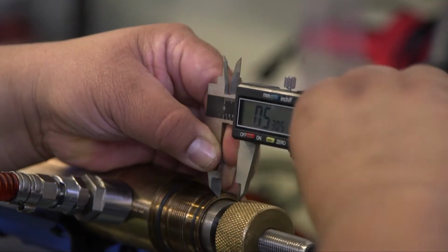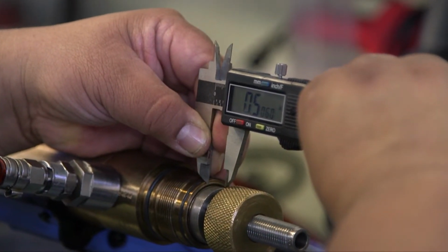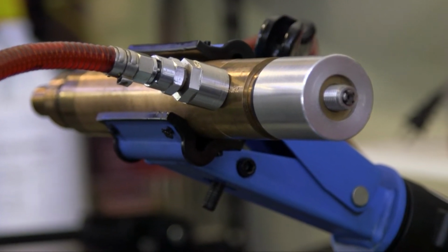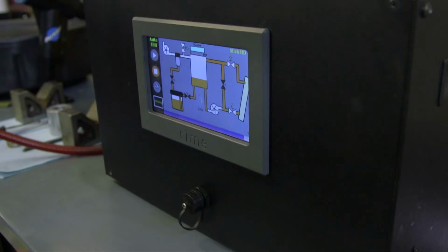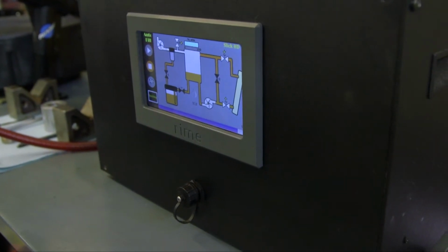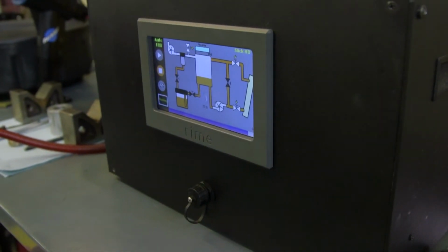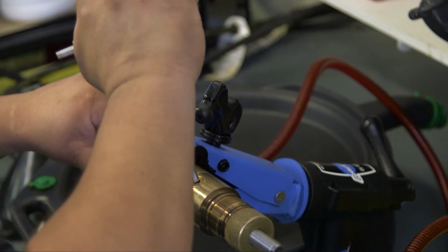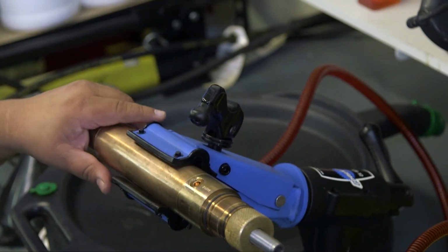The assembled pulsar drive section is now oil-filled using Rime's oil-fill station. Most of the way through the oil fill, the oil station stops and lets the user set the compensation piston to its correct position. After the oil fill is complete, the oil fill plugs are put in to seal up the compensation chamber of the pulsar.